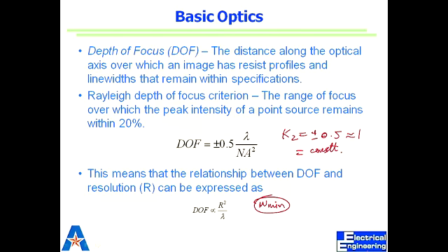If you have a feature which is a trench and you want to transfer some pattern there, this is your minimum depth of focus. Because if it's smaller than that, then registration will be messed up. Our light will not be in focus enough to transfer the pattern, to register the pattern accurately in size, or to expose the resist completely at that space.